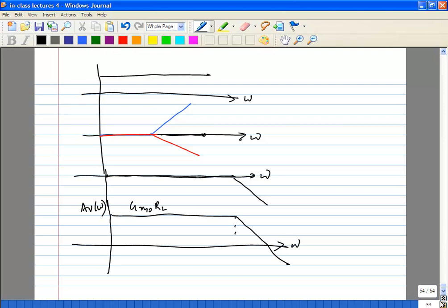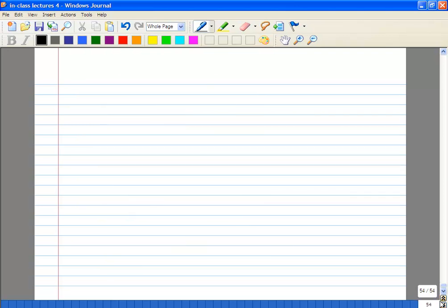Okay, so that kind of does it for your single stage amplifiers. For a single stage, you can maximize your bandwidth. Now, so far we have not considered the parasitics of the transistor itself. What happens if you just increase the FT of the device itself? There may be many cases where you might want that, because all things being the same, if you improve the FT, you can improve the overall performance.